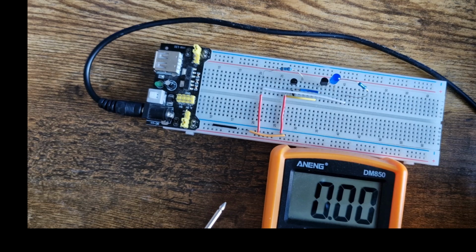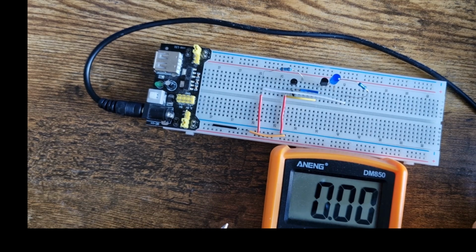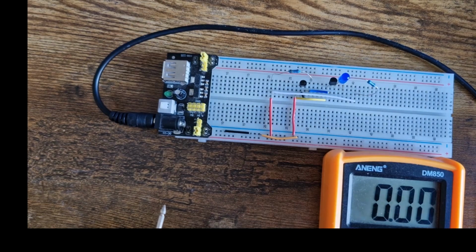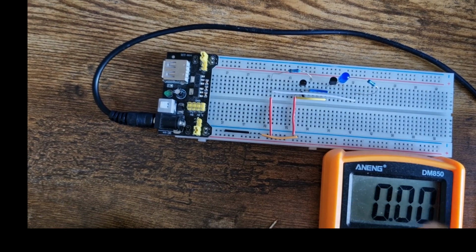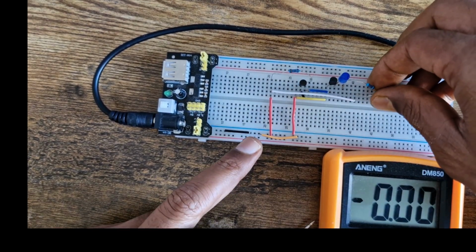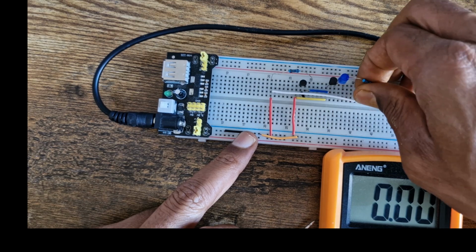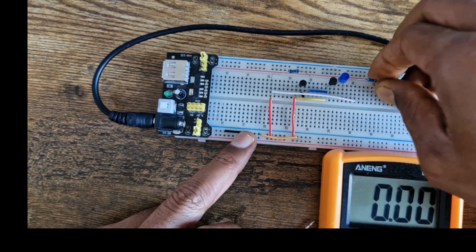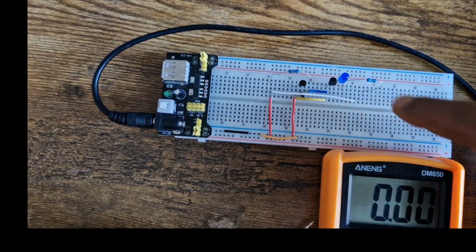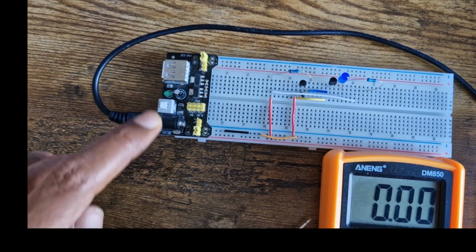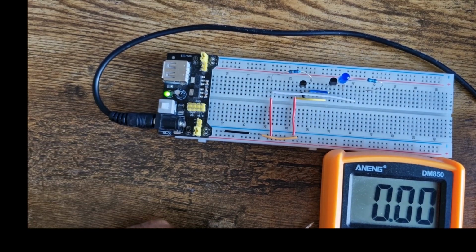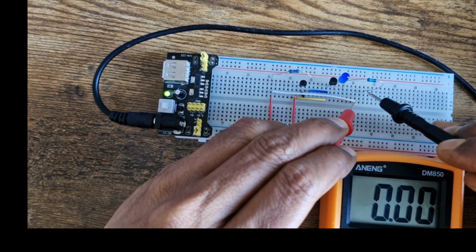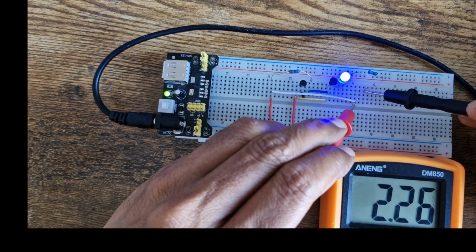We have to understand where to put it here. So we can break this branch at the point of the resistor, connect it somewhere here, and now that you broke the circuit, switch it on and put an ammeter, and you see the reading, and the circuit gets closed.